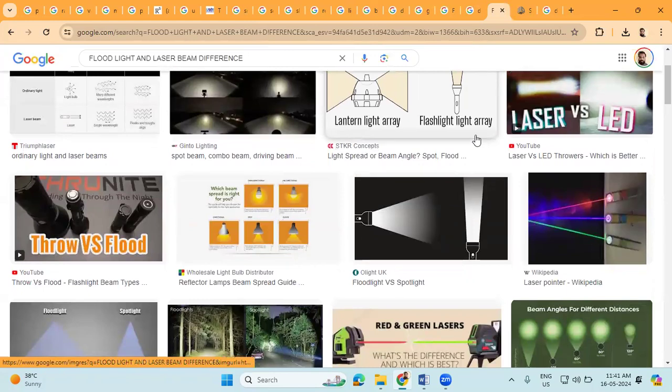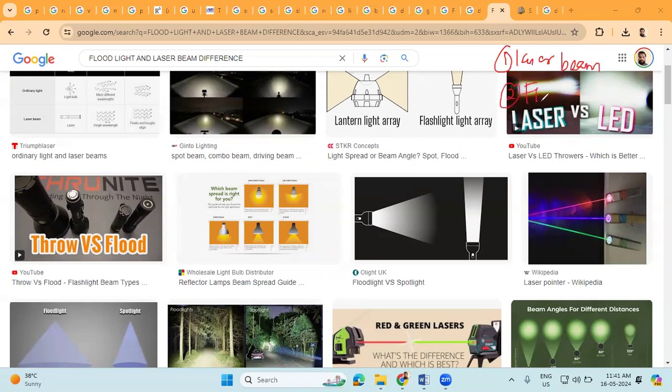In the context of the shape of UV light used in vat photopolymerization, it's worth noting that UV light can be employed either in the form of a laser beam or as a floodlight. Floodlight, as the name suggests, covers the entire area. It will cover an entire area like this. See this image.